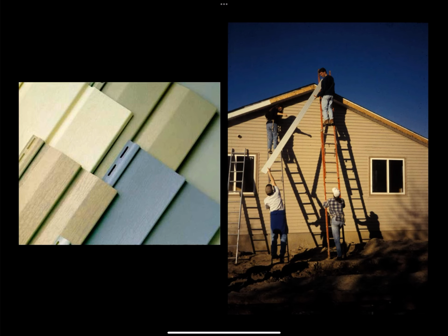So this is the least expensive metal cladding system, in which we take a sheet of galvanized steel. It is imprinted with a wood grain pattern and then coated with vinyl. And the coating takes place in a factory. It's a factory applied finish, and all of the bending and shaping is factory made. And this is designed as a substitute for clapboard wood cladding for buildings.